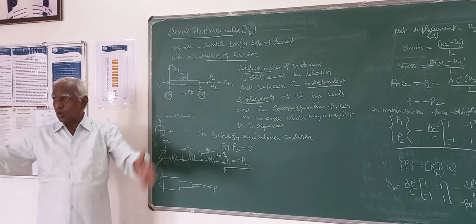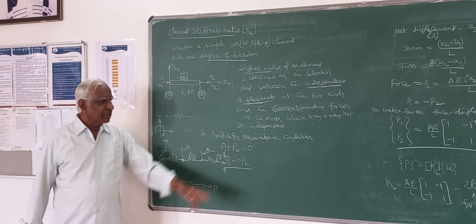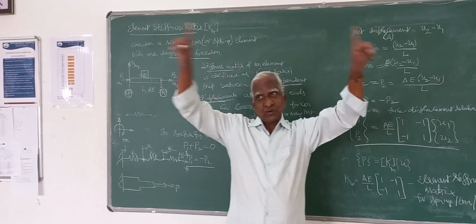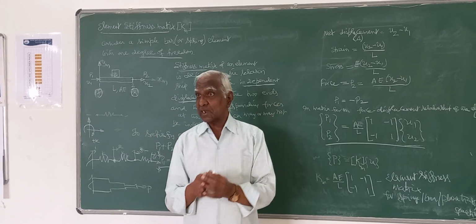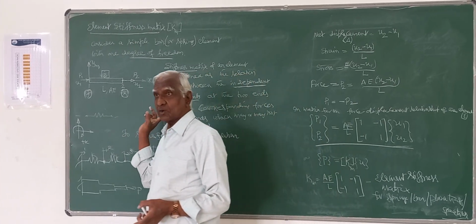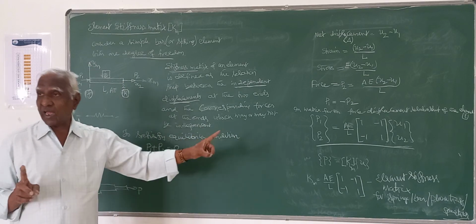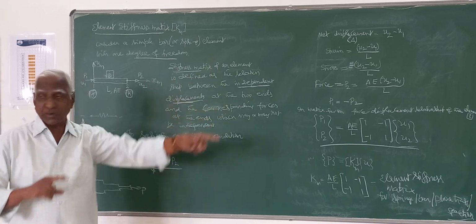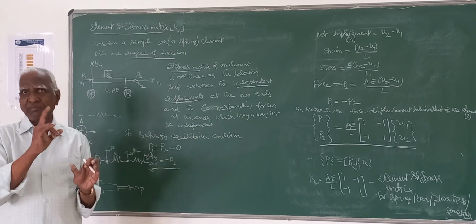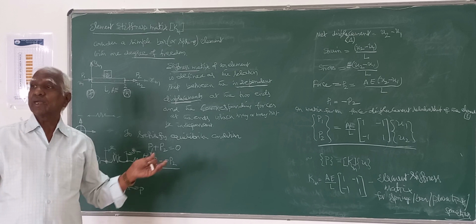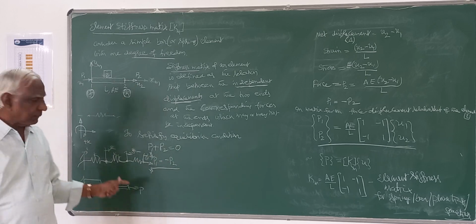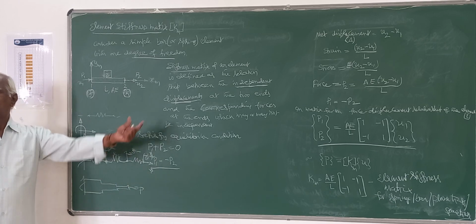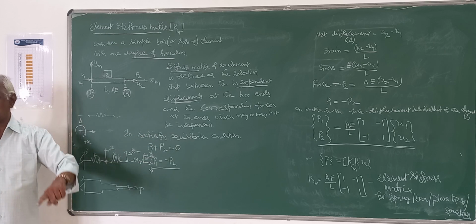Likewise, the total load matrix corresponding to this. Then use that relationship, P is equal to K times u. This K is for the total structure altogether, because the principle of superposition holds good. I told you the principle of superposition is valid. We can add the effects of displacements and forces, which I showed by the graph, together. The effect of one load, another load, we can add, all put together acting. Individually we can consider them element by element, and I can add them together by applying the principle of superposition.